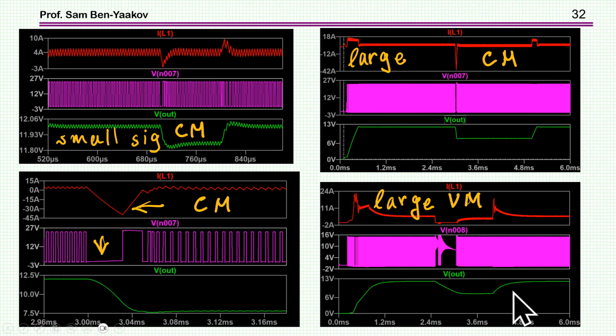At the on time, okay, and they increase the rise time here, we see that the current of the voltage mode is sort of tapering off, and therefore it's slowing down the rise, while you see here that in the current mode, the current remains high. So this voltage now jumps fairly fast. So you compare the two, you see quite a bit of a difference, although in general, they have the same switching frequency, the same crossover frequency, about the same phase margin.